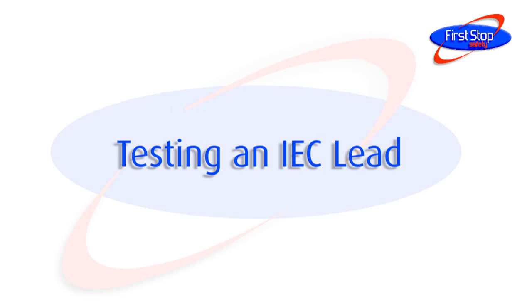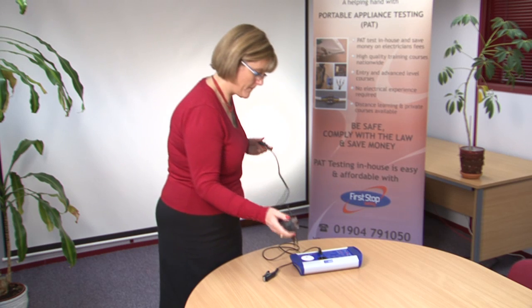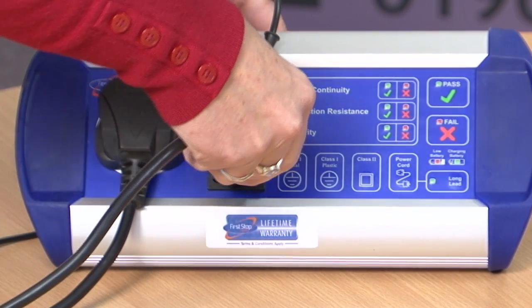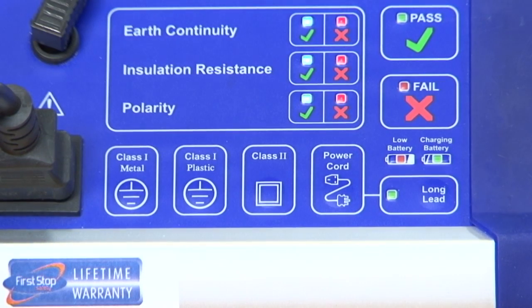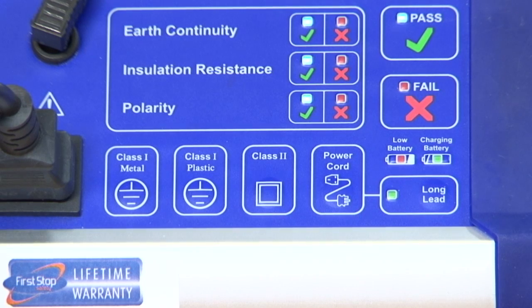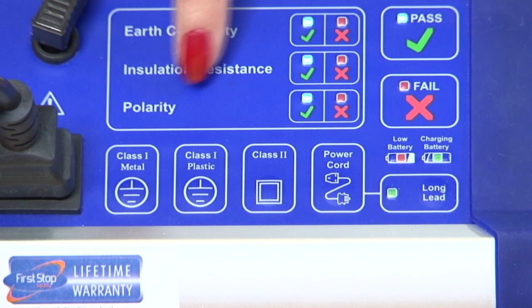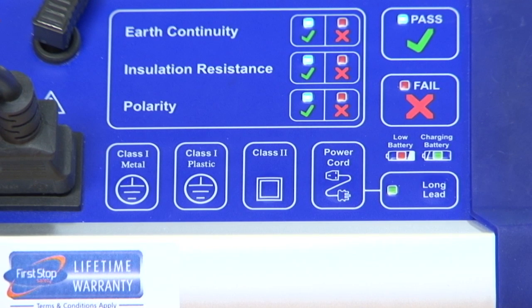Testing an IEC lead. The power cords used for PCs are commonly known as IEC leads. Most modern PAT testers have a handy IEC lead test facility. All you have to do here is plug both ends of the lead into the tester and test earth continuity, insulation resistance and polarity. The polarity test checks the lead is wired correctly. This can only be done if you have both sides of the power cord.